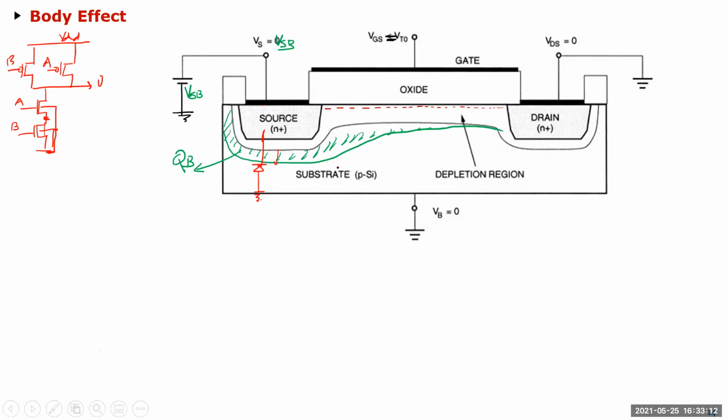So now the question is, what does the VT value change by? Because now what you have done is, we did this calculation where we said, okay, maybe if I show you the equation, that'll be more. So we have this extra charge now. So I'm calling this QB0.